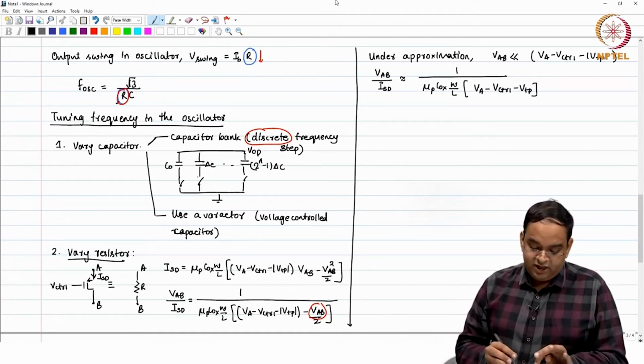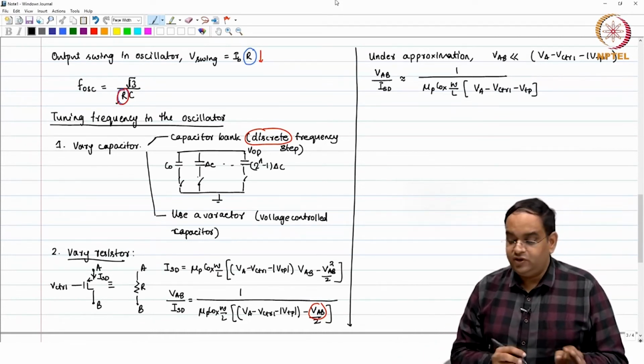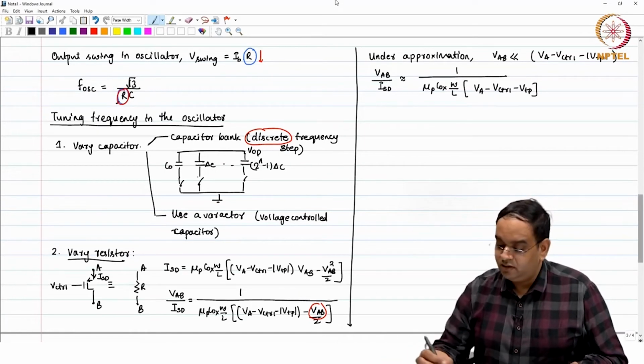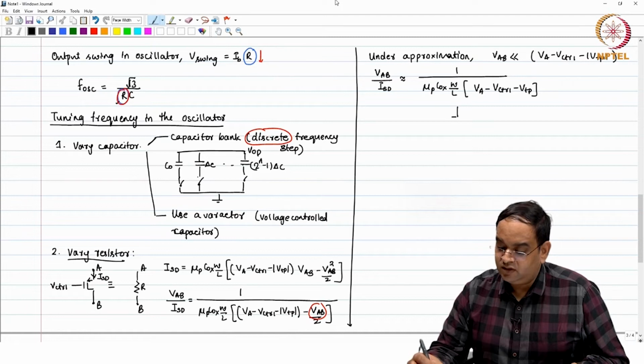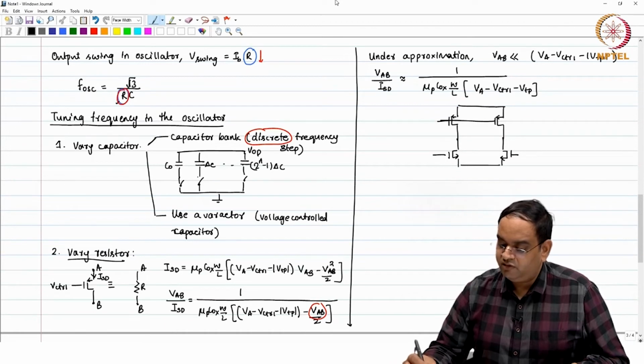Okay. And when this particular MOSFET is used in our current cell, and where was our current cell? Our current cell was, I am replacing the resistor with PMOS controlled by V control with NMOS input pair with a fixed bias current IB.